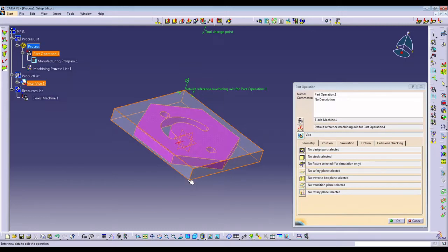You cannot start it here, because that means our tool will start from here. That is very wrong, because the cutting tool will then hit the workpiece or the table. It should be above the workpiece, so the minimum point is somewhere here.